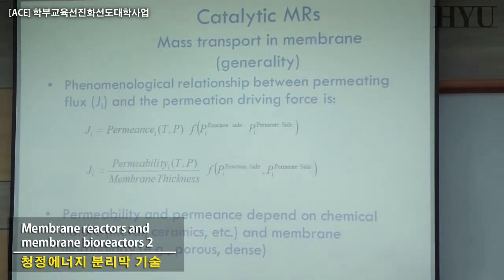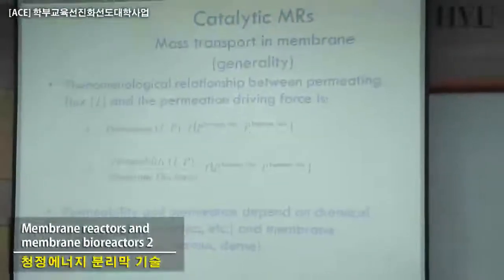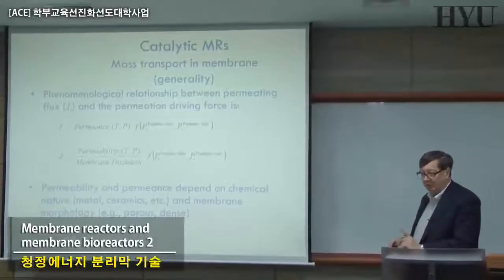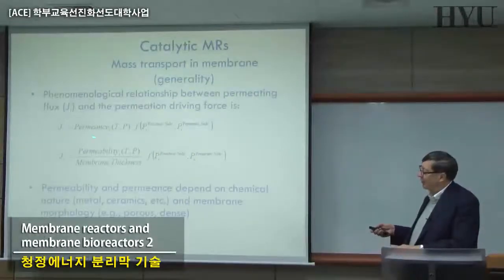And this difference can sometimes originate some confusion in the data from the literature. When you find some data, especially in gas separation, and you transfer to your data, and if you don't find good agreement, be careful to be sure whether you are talking about permeance or permeability.